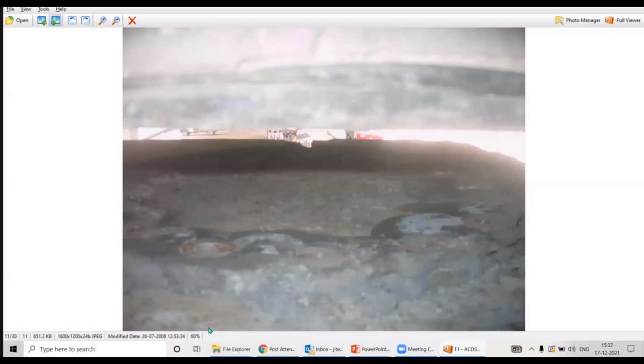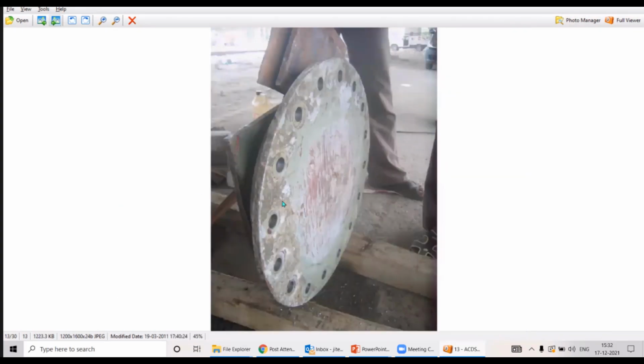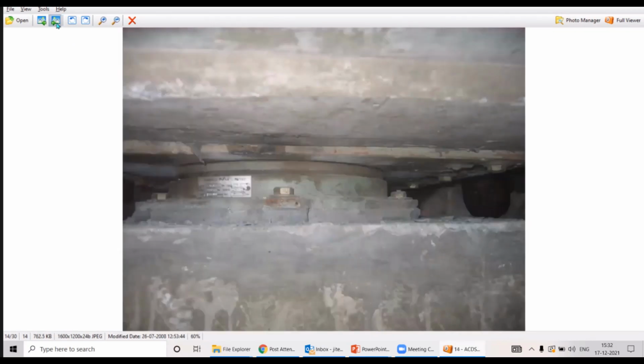And when we reached the inside, there you could see, I don't know whether it is visible clearly in the image or not, the grout material is only at the periphery, and at the inside central area where the load transfer is actually taking place, there is no grout. It is hollow. So imagine if the bearing is not supported by a firm concrete surface from underneath, how could it bear and transmit the loads? As a result of this, the entire bearing component bent in the hollow portion.